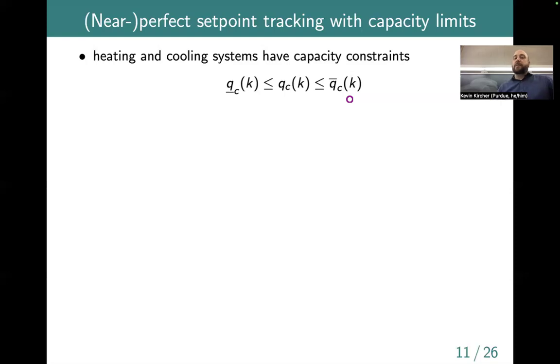Yeah, so the question is, why do building operators typically disable the cooling system in the winter? I guess the answer is they don't always do that. So there are building types where actually, even on a really cold winter day, you can have core zones, interior zones that have no exterior windows or anything like that. They're only like an interior office, for example. The grad student offices don't have windows, right? But they might have closed doors and they might have a bunch of computers and body heat and stuff like that. So there may be rooms inside of a big office building that still need cooling even on a really cold day. And so there you might leave on the air conditioning system for those rooms and use the heating system for other rooms.